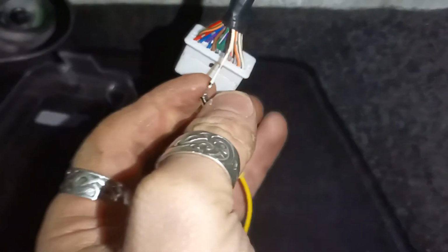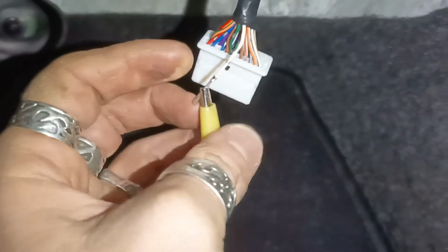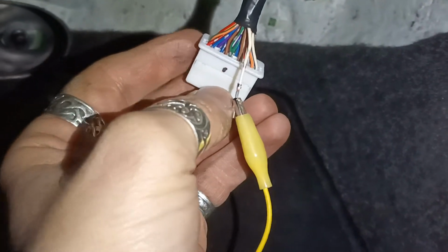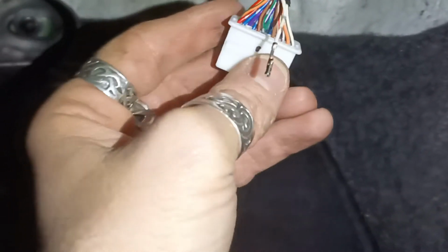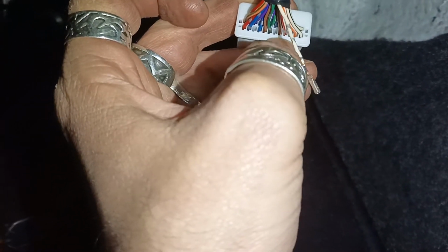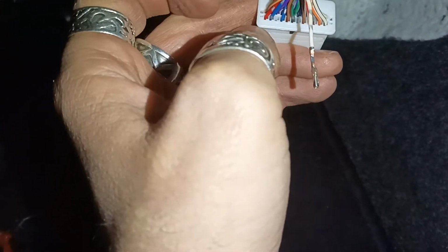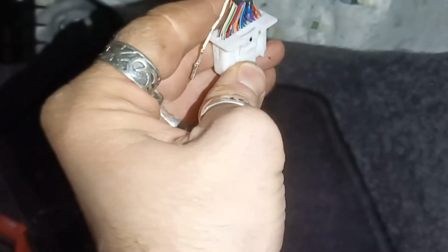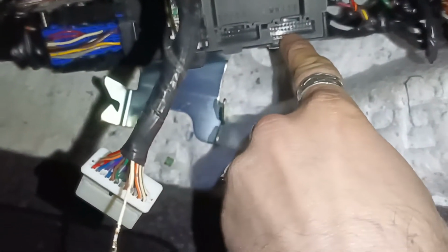Okay, so I have found the white cable. That's the white cable that's coming from the auto pin of the headlight switch, and it's this hole right here. You can see the hole here. It's the 7th in this row, not from the clip side. That's the clip, not from the clip side, the 7th one, and the connector is here. That's where it says white.